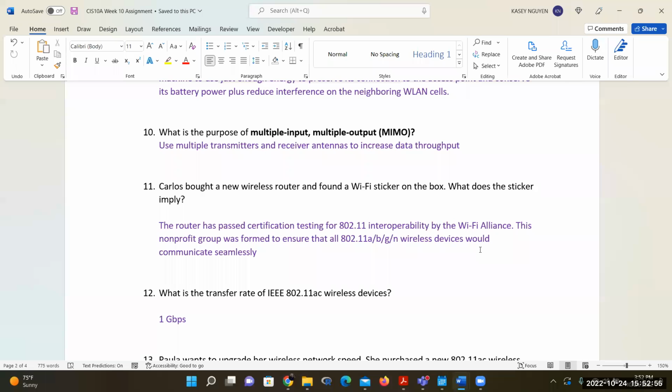You have to go through the historical organizations that oversee these buildings. And even if you own the building, sometimes you cannot do a lot of modifications to it. Because they want to keep it in shape like how it was, you cannot install a lot of these wires, right? So my workaround is, if they're allowing you to drill things on the wall, sometimes we actually put a false wall and then run the wire behind it, to not attach it to the original wall.